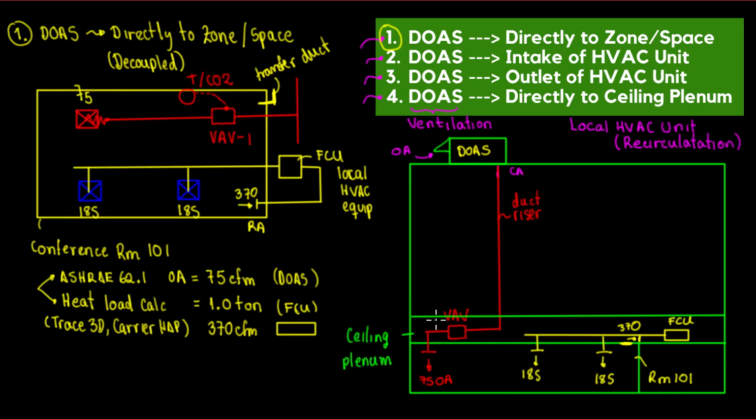The ceiling plenum is the space between the deck or the slab and also the ceiling ACT tiles. This is very important to coordinate with the architect, because if you have low spaces, for example, they give you 12 inches and you already agree with that, it's very difficult to accommodate all these devices and ductwork. Remember, this is only HVAC. What about piping? What about fire protection? What about some cables, electrical? So you need to accommodate as much space as you can get.